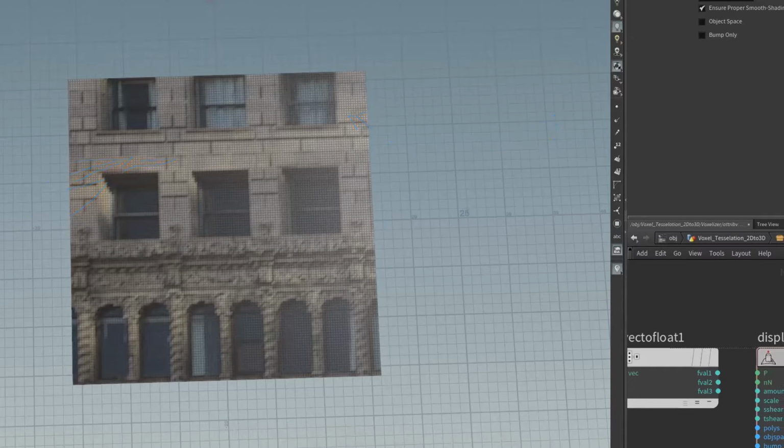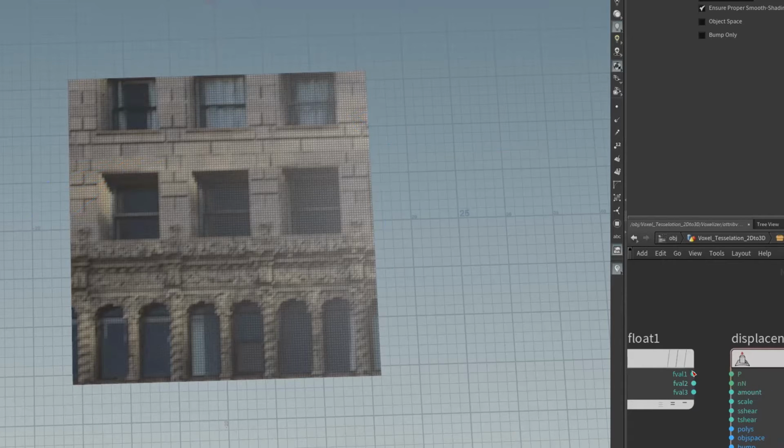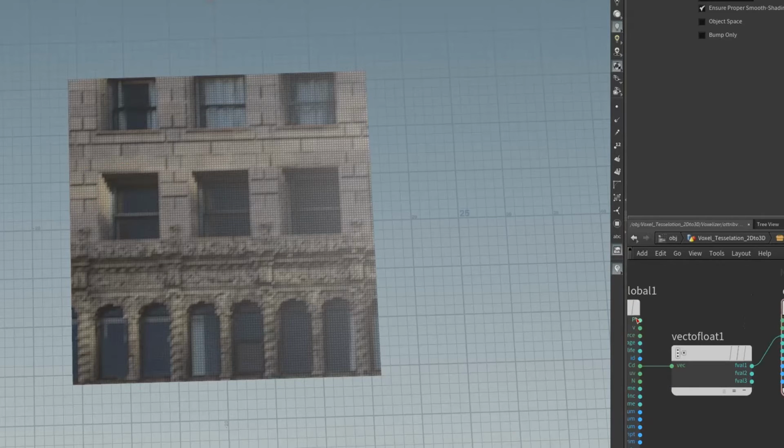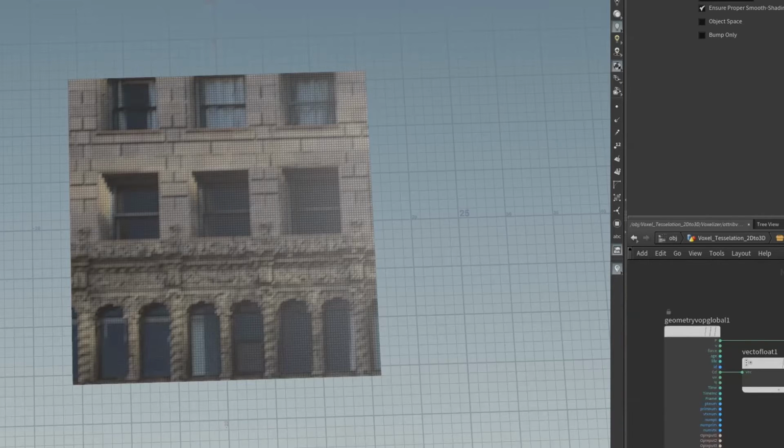But Houdini is nice so that they have everything in as a function. So we connect this to the amount, and we use this displace P to the P. But for now nothing happens, because we didn't connect this P information to the displacement. And I said that this already has normal information. So what you need for that normal is a display N to be connected to the N. Then our job is done here.